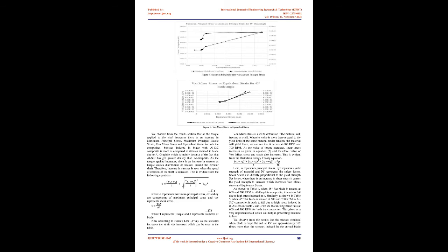Power number is considered similar to friction factor or drag coefficient. It is proportional to the ratio of the drag force acting on the unit area of the impeller and inertial stress. Inertial stress is dependent upon the momentum of the bulk mass of the liquid. The terms used are listed in table 1.